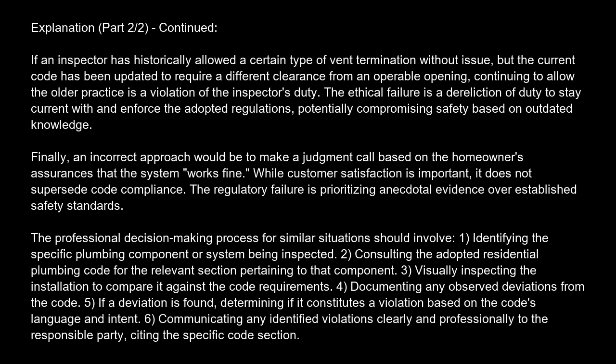The professional decision-making process for similar situations should involve: 1. Identifying the specific plumbing component or system being inspected. 2. Consulting the adopted residential plumbing code for the relevant section pertaining to that component. 3. Visually inspecting the installation to compare it against the code requirements.